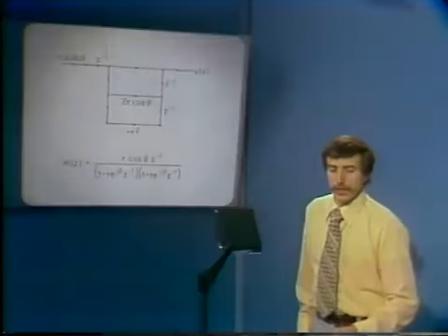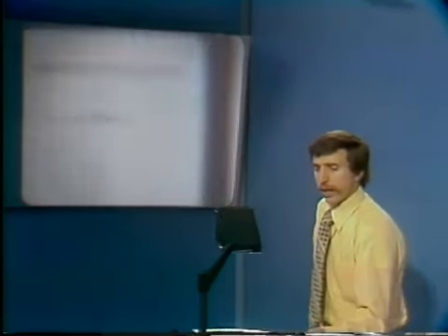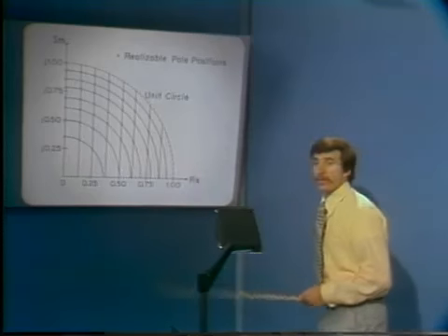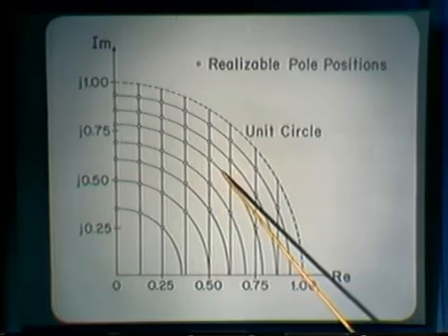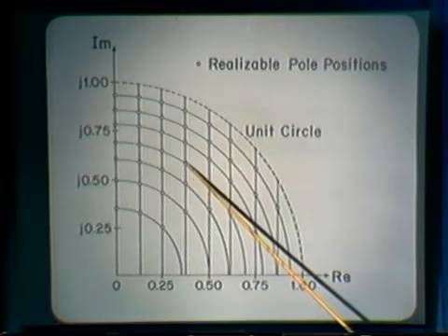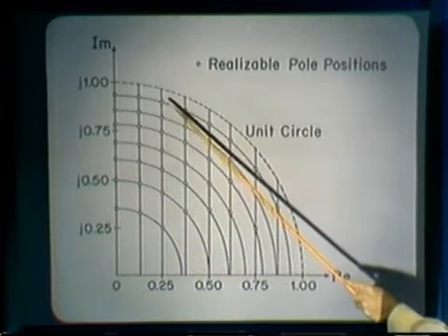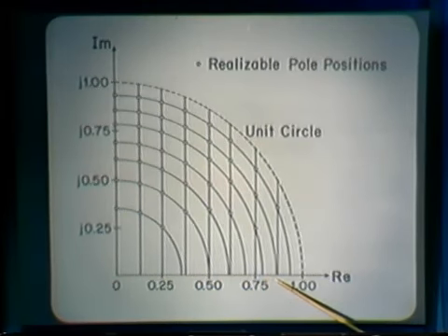What this implies in the z-plane is that, let's say, for a choice of register length for this particular case equal to 3, for a 3-bit register length, the pole locations which can be implemented with that system are restricted to fall at the intersection of the grid points that I've indicated here, due to the fact that quantization of the parameter r cosine theta implies that we must lie along lines equally spaced along the horizontal axis.